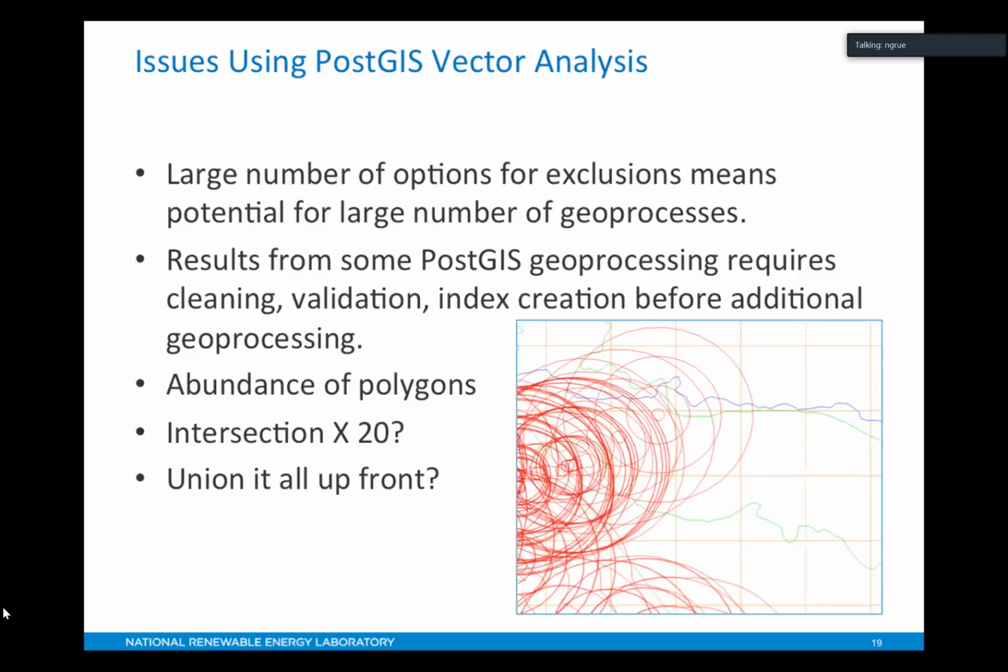And so this image here down in the right kind of shows what you would find. You have grids that are maybe the DNI data sets, and then urban areas and wetlands. And then you see the red circles, and those are actually buffers to either cities or roads. And as they expand out, you can see how they overlap, and you just start creating these teeny tiny little sliver polygons. And all these polygons really add up when you're considering 15, 20 different layers.